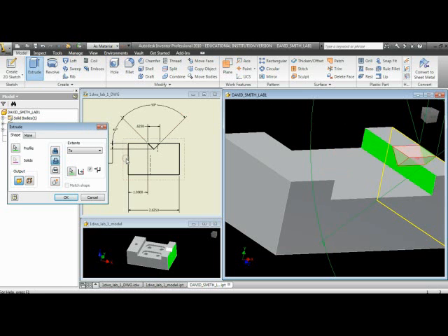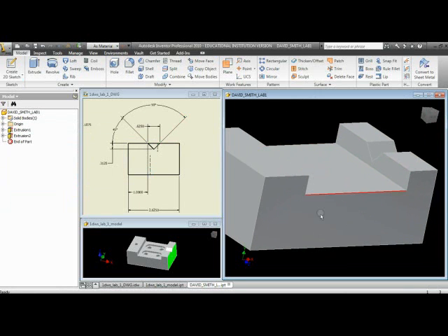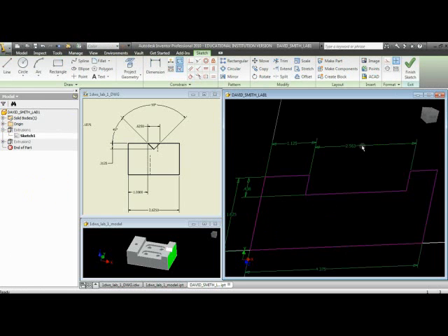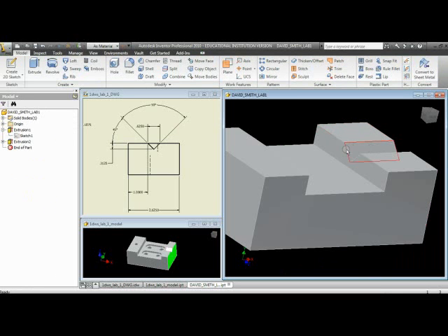Again, F4 function key, I'm going to rotate that around. I'm going to right click and do the zoom thing again. Whoops. I don't have my zoom on there, so I'll use the wheel to roll that towards me to get it closer. And I'll hold that wheel down to pan. So hold the wheel down, move your mouse left or right, up and down. That pans it for you. Push the wheel away from you, the picture goes farther away. Pull the wheel towards you, the picture comes closer to you.